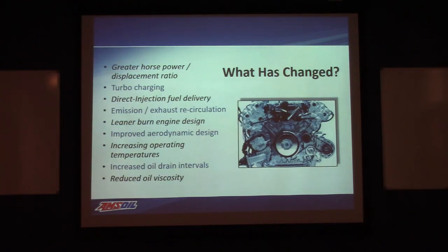Also, we know, looking back at lubricant fundamentals, that the thickness or the grade of the oil, its viscosity, or I should say load carrying ability, is directly related to that grade. The heavier the oil is, the greater the load it can carry. But what we're trying to do now in an effort to improve fuel economy is put lighter and lighter oils in the engine.